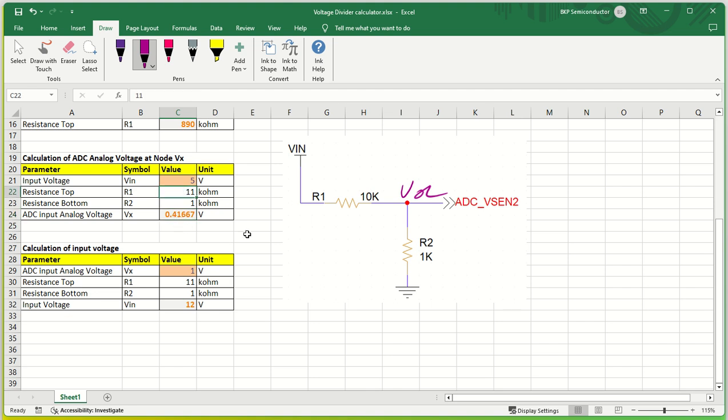If you want to change R1 to be, let's say, 10 kilo ohm and R2 to be again 10 kilo ohm, so this will be half of that, that will be 2.5 volt. So you know I already calculated, right? If it will be 3.3, what will happen? Both are 10 10, so this will be half of 3.3, that is 1.65. So it will be 1.65. Understood? So this is how you calculate the node voltage when you have R1, R2 and input voltage known.